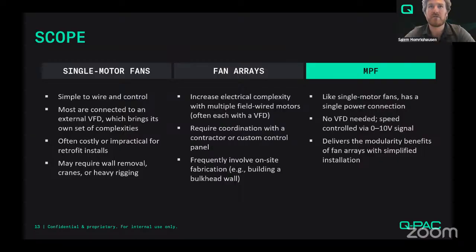Then you're going to have to figure out some kind of control scheme. So are you going to use VFDs? Are these just direct drive plenum fans that require VFDs? How are you going to control them? Are you going to have one VFD per motor? Are you going to have multiple VFDs? These are all decisions you have to make and different trades you have to coordinate.